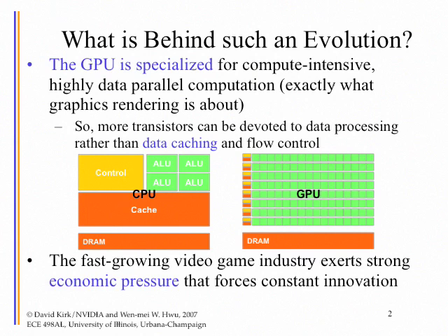Okay, whereas the GPU design is based on a somewhat different philosophy. It says, I'm going to design the equivalent of a CPU core with a very small amount of memory. So I'm not going to try to put a lot of cache memory on the chip. Okay, I'm going to just put a small amount. And so I know that whenever I execute, I'm going to have essentially a little bit of control, a little bit of cache, and then a huge number of units.